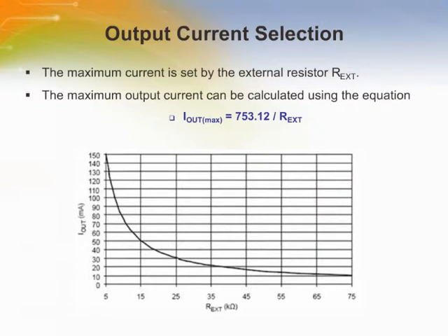The overall maximum current is set by the external resistor REXT connected between the REXT and logic ground pins. Once set, the maximum current remains constant regardless of LED voltage variation, supply voltage variation, temperature, or other circuit parameters that could otherwise affect LED current. The relationship of the value selected for REXT and I out is shown in the figure.